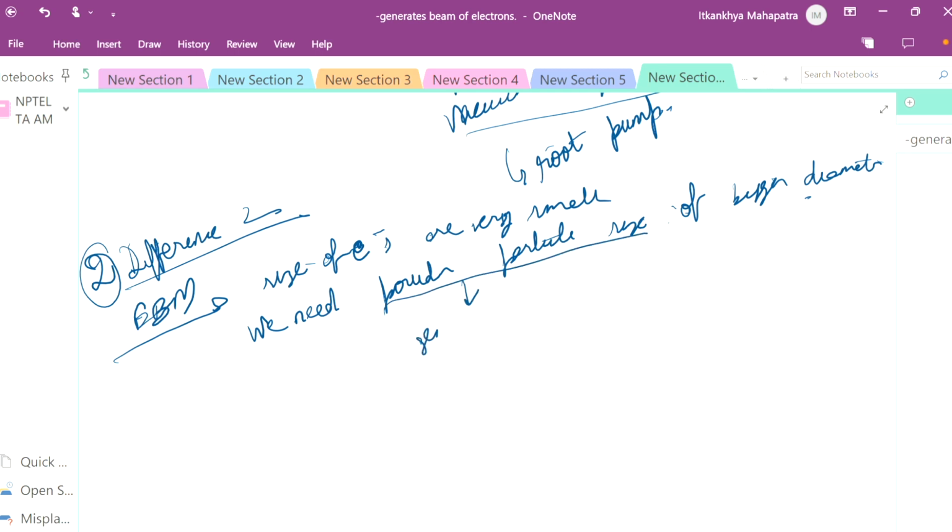Now, this is generally 15 to 30 micron. It may also go to 60 to 90 micron. For this process, we need to take powder particles of bigger diameter. Because of this bigger diameter, what will happen? The surface roughness is higher.